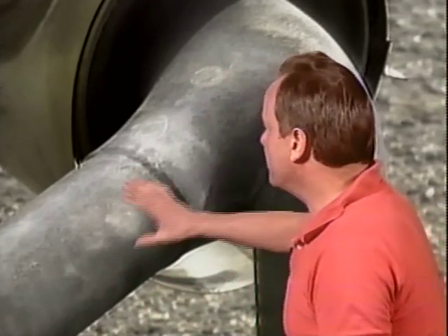They also say, why do you have ball joints in reciprocating engine exhaust systems? And the answer is to allow movement. And how loose should they be? Loose enough to permit some movement. So if you have a ball joint in an exhaust system, it's there to permit movement because of all the heating and cooling and expanding and contracting and the engine moving and so on.